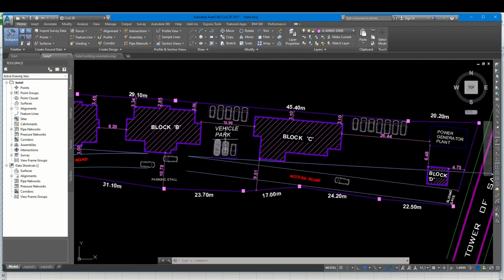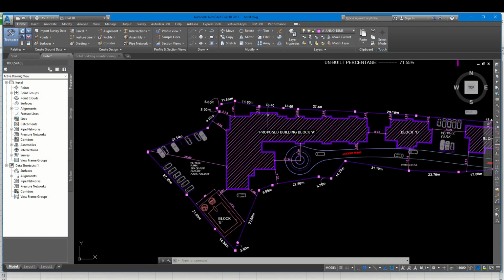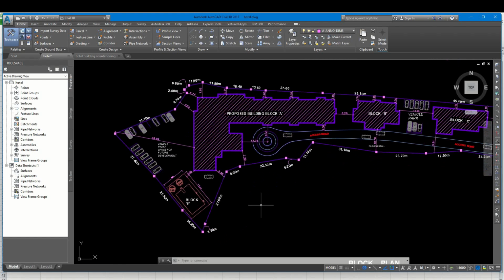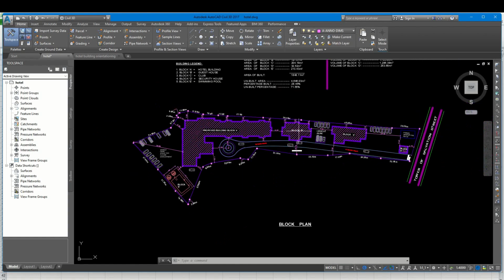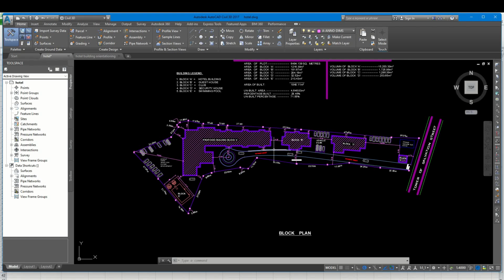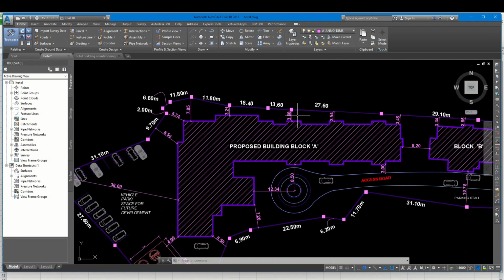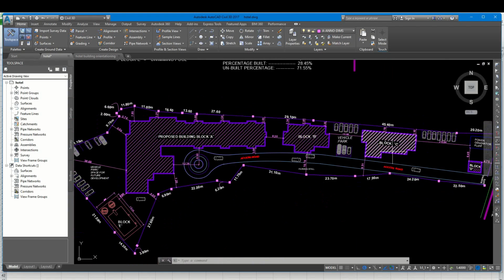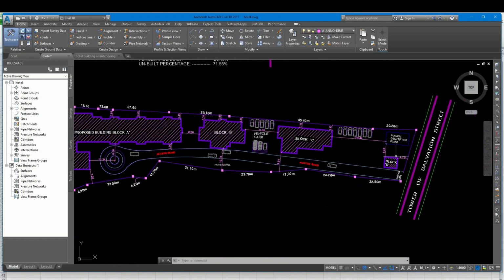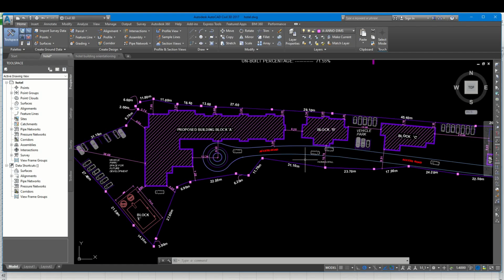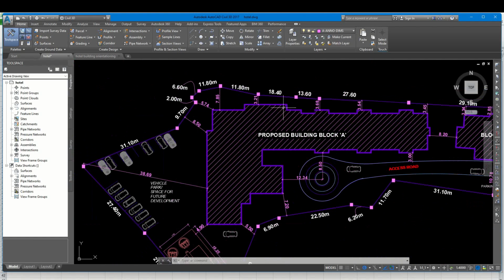Again, I will look at the building the way it looked in the site, and I noticed that the architect must have gotten his information and did his design based on the information that was given. But now I want to orientate this to the original site, keeping in mind whatever measurement they have. If I cross-check and maybe one or two of these are not okay, then I will be taking off exactly with a new measurement to get the building on its new site, and I mean the original site.